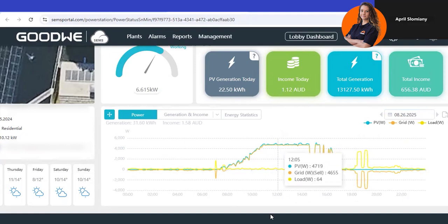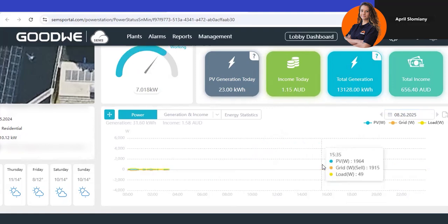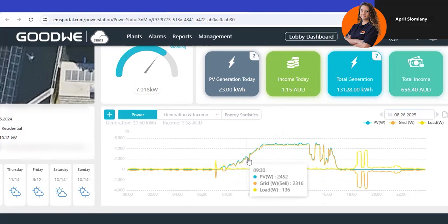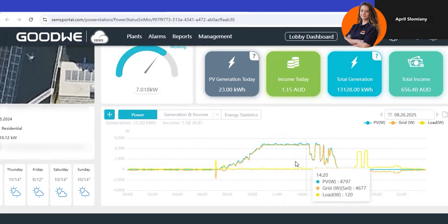Your home might also be subject to something called flexible export. That is an export limit implemented by SA Power Networks, essentially to assist with grid control. There will be some homes that are export limited to 1.5 kilowatts. So for example, on this home, if there were no loads on in the house, you would see the generation on the system drop down to probably a little bit above 1.5 kilowatts. So somewhere in this realm under your 2 kilowatt bar graph. Usually flexible exports affect homes more in the summertime.